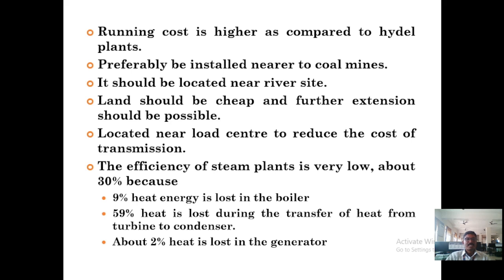It should preferably be installed near coal mines. It should be located near a river side because we need a huge amount of water to run the thermal power plant. The land should be cheap and further extension should be possible. Also, they are located near the load center to reduce the transmission cost.